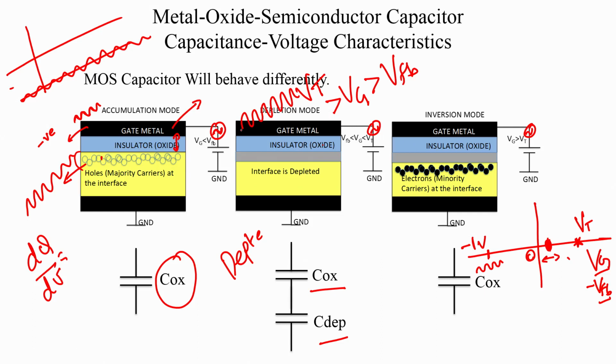So, how does the semiconductor respond? It responds by increasing or decreasing the depletion width. So, the XD increases or decreases in response to the applied voltage, and by increasing or decreasing the depletion width you are either covering or uncovering all the fixed ions.